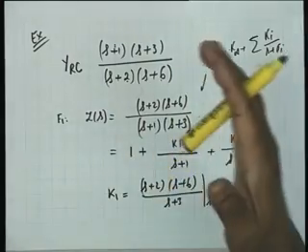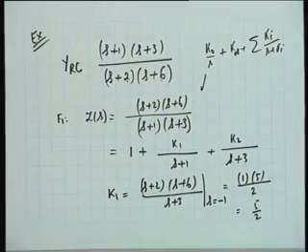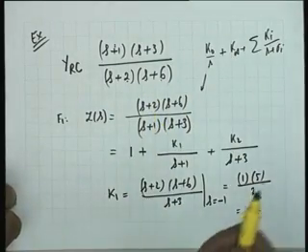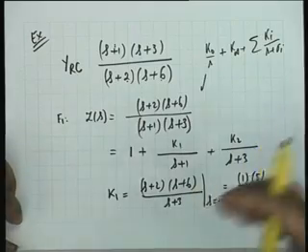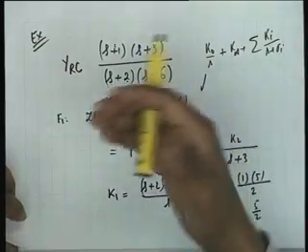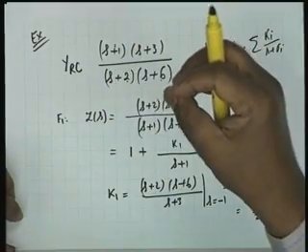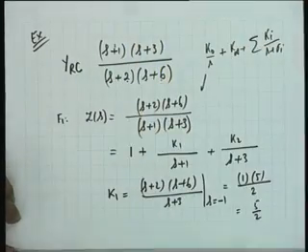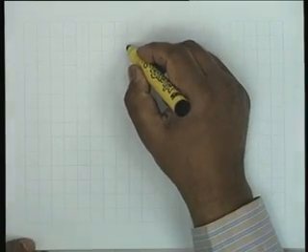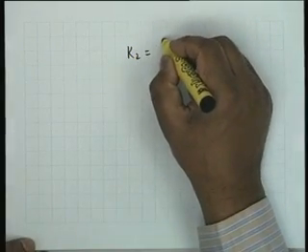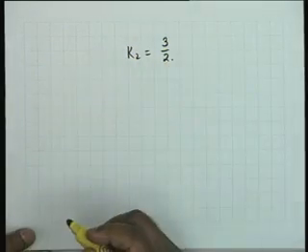If you truncate somewhere in a continued fraction, things will not cancel. Because Foster 1 is an end by itself, you do not have to do anything further. But in Cauer 1 or Cauer 2, once you truncate, you are in trouble. So, do not truncate. Similarly, you can find k2 is equal to, if I am not mistaken, 3 by 2.